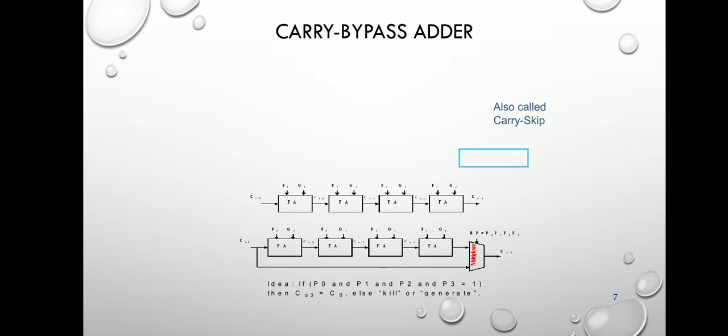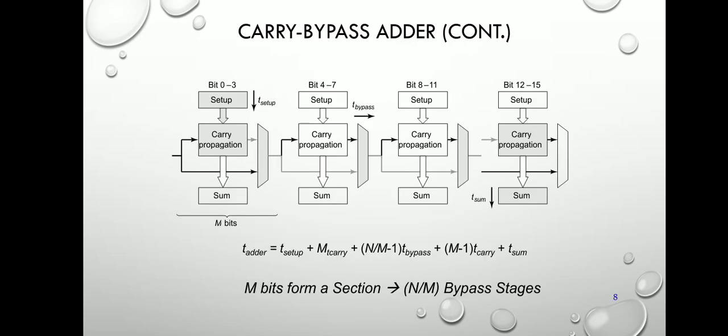The major disadvantage is it can skip carry only when all bits are in the propagation condition. It is not certain that every bit is always in the carry propagation condition, and if it is not in the carry propagation condition, this will get delayed. Otherwise, if it is in the propagation condition, the propagation delay will be reduced. This is one of the fastest adders, used in many data processing processors to perform fast arithmetic functions, and it performs addition and multiplication in very little time.